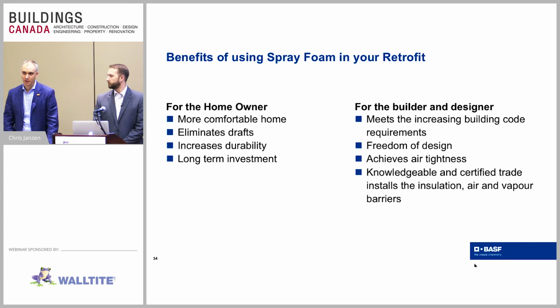It's the temporary bracing, where you're looking to use the T-bars, that kind of stuff, during construction itself. We've done engineering structural testing. We actually have engineering reports that we can send out to you that show that spray foam going into a stud assembly is a lot stronger than a traditional OSB and drywall 2x6 wall. Will we see recognition of that? The OBC doesn't really call out for that, is my interpretation of it.